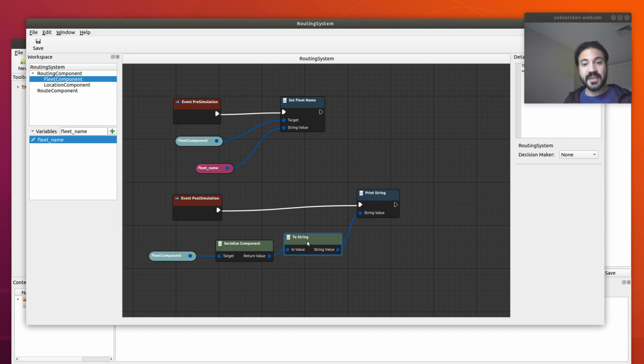Very good. One thing I want to mention is that you see that here you have green blocks and blue blocks. What are these things? Well, we are talking about pure functions, which are the green ones, and non-pure functions, which are the blue ones. The distinction is that pure functions are not modifying any object, and neither the environment or our GUI. So they are only getter functions or, for example, operators or converters, right? Converters. So, for example, the toString converts one element, one type, to a string type, and doesn't modify anything else.